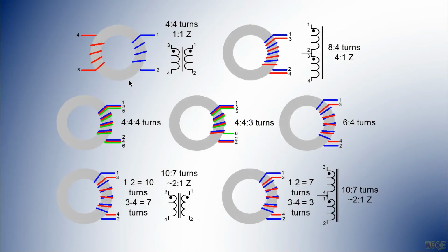And in conclusion, some typical coefficients of coupling would be for air-coupled coils where the coupling is desired between the coils, 0.1 to 0.6 are typical coefficients of coupling. For air-coupled coils where coupling is undesired between the coils, you will typically mount the coils as far apart as possible, and you'll try to mount them at right angles. If you mount them at right angles and you keep the coils separated by about a diameter apart, you can get numbers like 0.01 pretty easily.